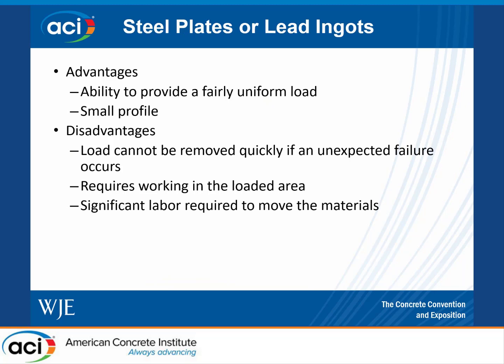Talk about steel plates or lead ingots being used also. One of the advantages is the plates have a fairly small profile, so you can put a large amount of weight in a small area, and you can also use them stacked on top of each other to provide a fairly uniform load or a line load in some cases. Again, the load can't be removed quickly if you have an unexpected failure, and this requires working in the loaded area during the course of the test to move the materials in and out.